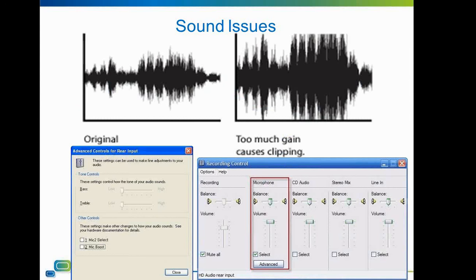Next issue source is microphone overload. It might be caused by microphone boost enabled or too high gain value from microphone. It is not recommended to use microphone boost in any case, because it is making microphone catch more noise than always, causing the sound to clip and corrupt. If you hear dispatcher with some buzzing noises over specific letters in speech, or sound from dispatcher is getting better when dispatcher is not speaking directly to microphone, decrease microphone gain.